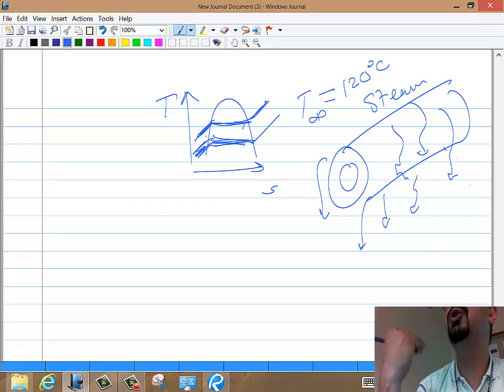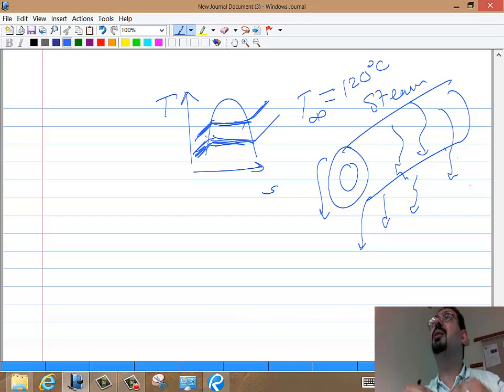So in a power station, usually the condenser is at a very low temperature. They like to make it condense at very low temperature so the turbine has a lot of room to expand. The steam in the turbine expands from the high pressure in the boiler all the way to the low pressure in the condenser. So the lower the condenser pressure, the more space you have for the turbine to run, right? Huge expansion means a lot of work you can get. So they take the pressure in the condenser as low as they can.